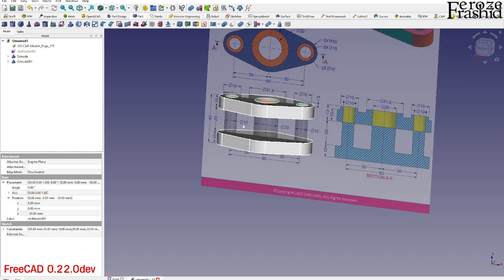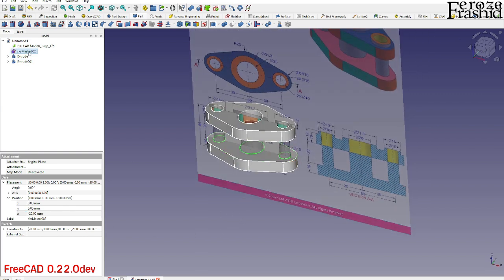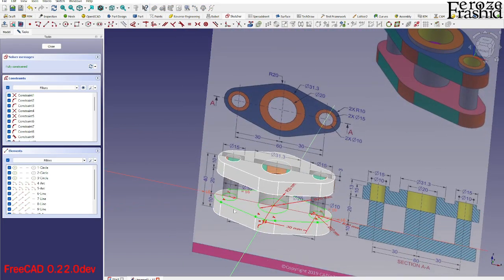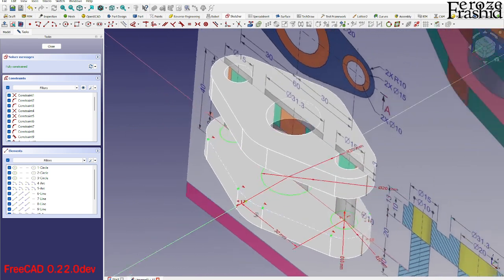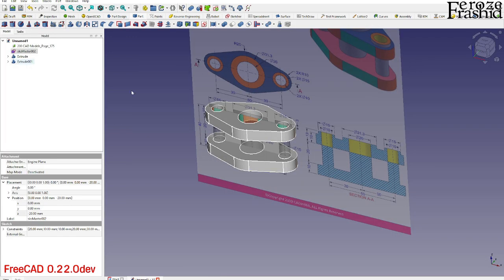Now there are these 3 cylinders that I'll have to build. I can use this sketch, bring it down 20mm, right? So say -20, and on this one I want to get in and actually take the outside edge. So double click on one of the edges after selection, and that will select the whole thing, and hit make construction geometry. So that's GN, G as in God, and that's a shortcut to make things construction geometry back and forth. Right, so now we have only the cylinders.